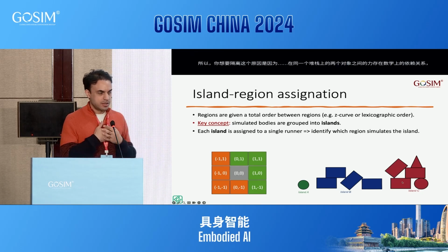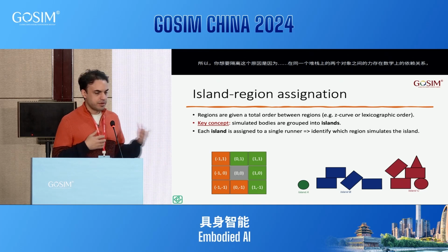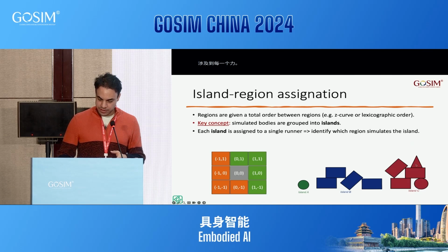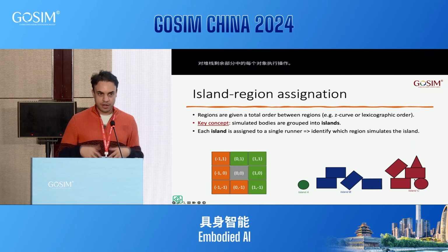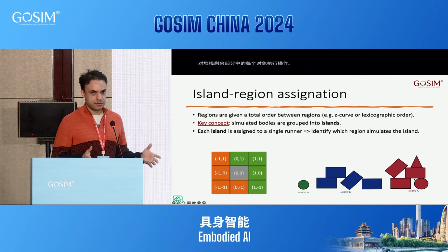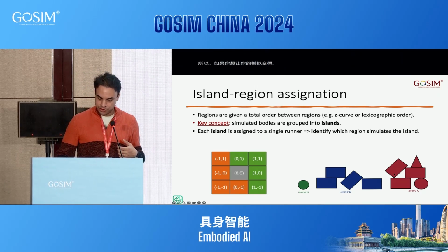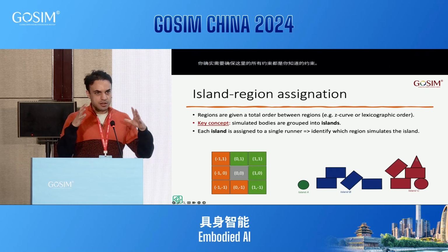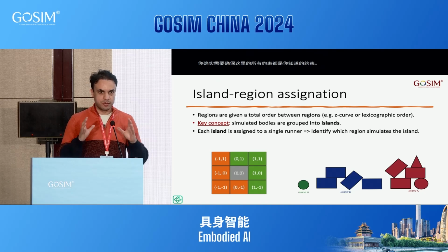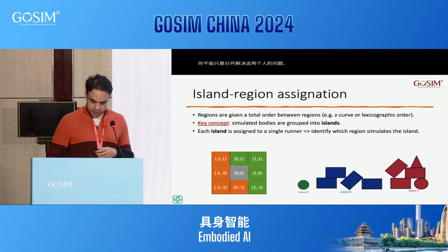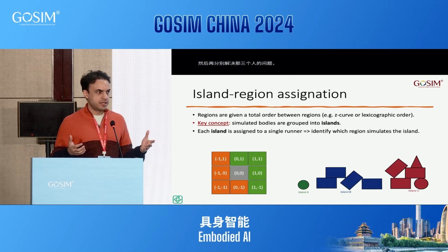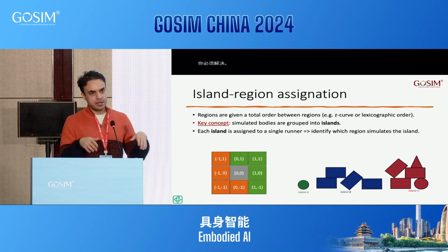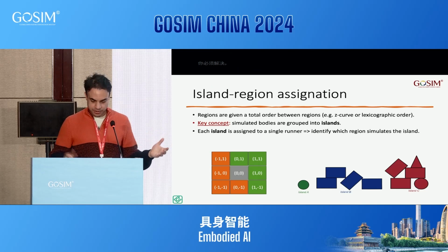If you want your simulation to be correct from a numerical perspective, you really want to be sure that all the constraints here are known to your constraint solver. You cannot just solve these two separately and then these three separately and hope that it will work. It's really a global optimization problem you have to solve. So the concept of island is basically how many objects need to be part of the same mathematical problem to create a correct result.